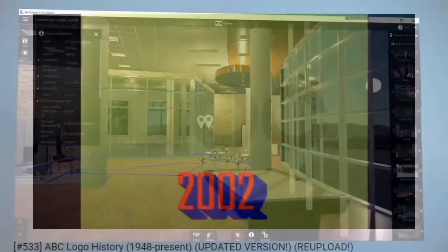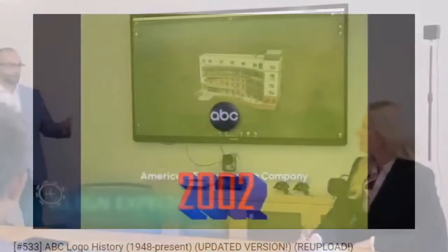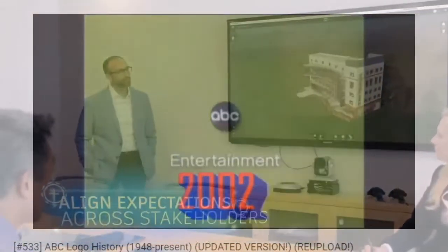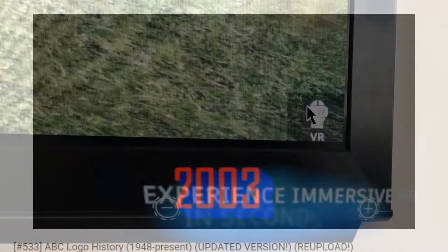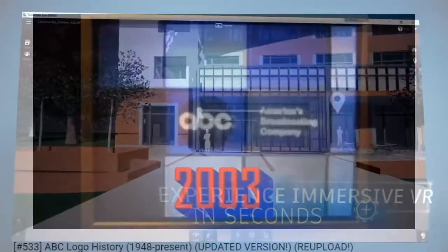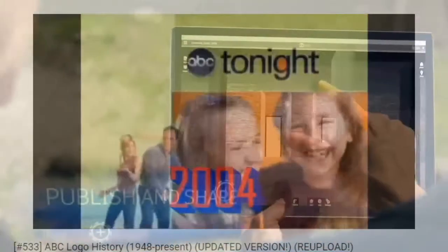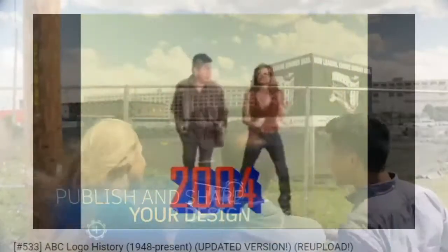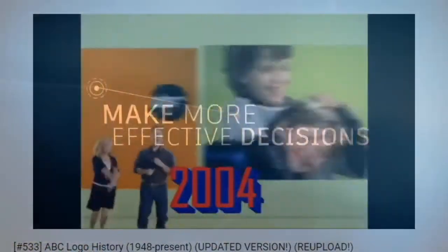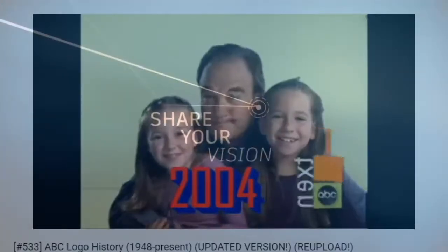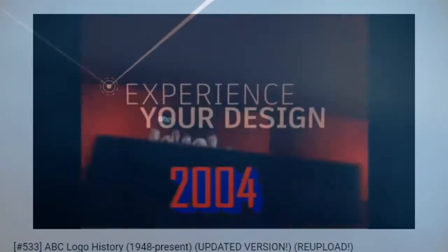Pick all 4 bottom edges of the floor slab at the level of main ground. And we've done this. So if we click this one, oops. I don't see this one. There we go. If necessary, orbit the 3D view. I just screwed that all up. I picked the edge, not the floor itself. So let's do it again like this.